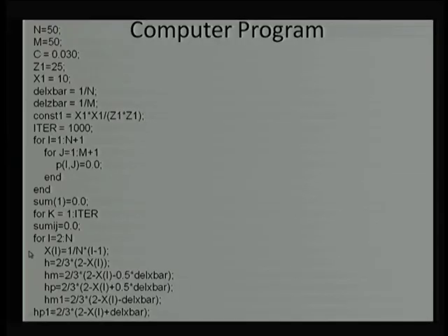We do not have to calculate, or we do not have to reassign, okay, it is 0, it is 0, it is 0. We say that it is inbuilt 0. Now, you take all those 0 values and calculate the remaining pressure. That is why the first node and the n plus 1 node have been removed here. We know the pressure at the n plus 1 node and we know the pressure at the 1 node. We do not have to recalculate those. That is why this loop is from I is equal to 2 to n.